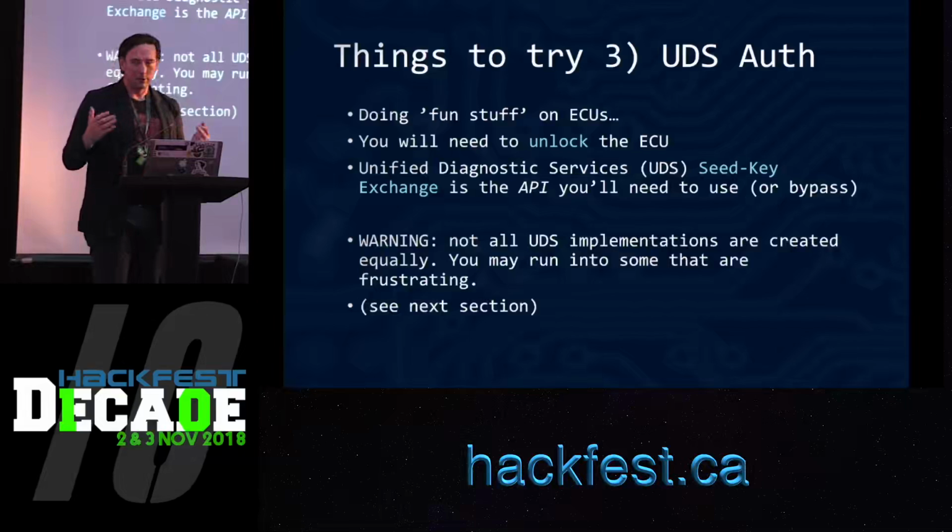So if you have one of those little Bluetooth adapters and you have the Torque app for your Android or something like that, or maybe you have a scan tool, those things are all using UDS to scan the fault codes in your car. That's why UDS was created, for those fault codes for emissions tests. But it's grown because once you put a feature in there that's kind of extensible and has that transport layer, the automotive engineers just start adding things on top of it, right?